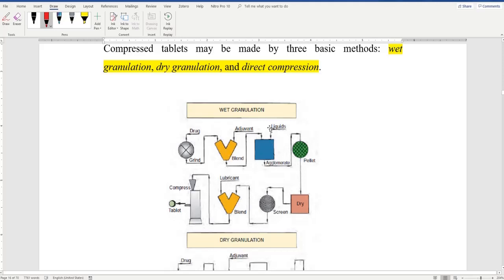طيب, then you add the binder solution or adhesive solution, and you know why we need to add the binder solution. This is to allow the particles to stick to each other, and you will have wet powder or damp powder here. Then it's better, before you dry the damp powder, that you granulate your wet mass to cut them into small pieces.